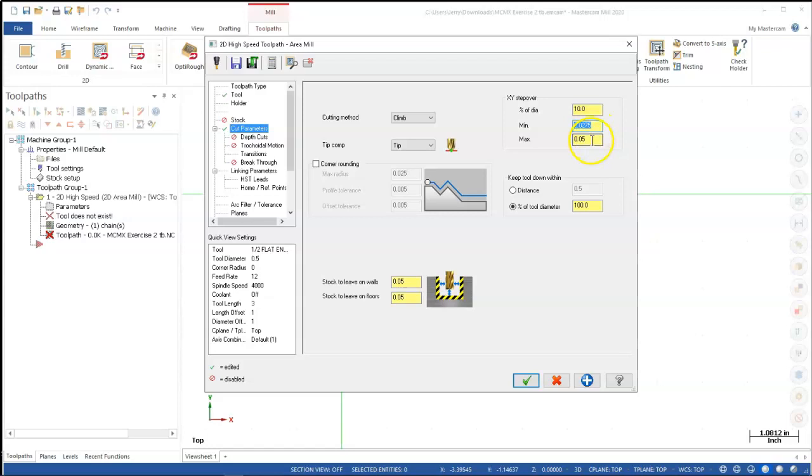They go to 0.27 and a max of 0.50. For a half-inch tool, that seems like a little bit. Consider that we're going to go a half-inch deep when we're going around this part. So as we increase the depth, we take a smaller radial cut, and we're able to increase the feed rate. Right now, first pass, I still want that feed rate kind of low because I don't want to scare myself on the first engagement. If it's machining reasonably, I can get a little more RPM and a little more feed rate out of it, then I can make those decisions and come back on the second or third generation of the program and make it that much more efficient.